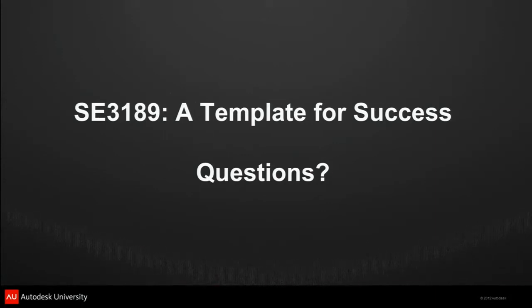Does anyone know the answer to that question? It seems quite standard. It's probably part of the system family. Yeah, I haven't been able to find it anywhere, but you lay out a page of sections and they've all been cropped, and they'll be quite a bit past where you want them, so we have to move them all the time. Yeah, it's true. It also affects whether your section is a detail or building section, in the scale of it. So if it's detailed, the name's supposed to be closer.